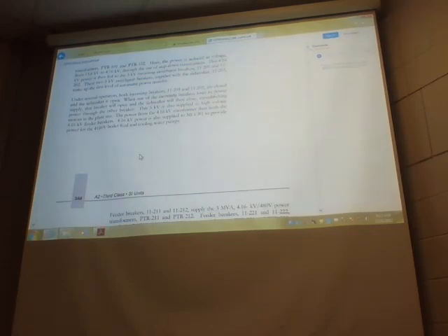This 5 kV is also supplied to high voltage motors in the plant. The power from the 4160 volt transformer then feeds the 4160 feeder breakers. 4.16 kV power is also supplied to MCC number 1, which is motor control center number 1, to provide power for the 4160 volt boiler feed and cooling water pumps.